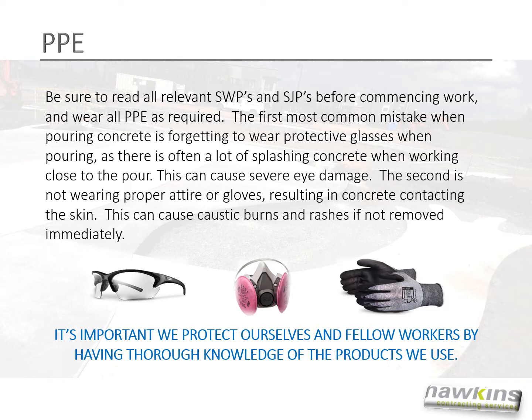The second is not wearing proper attire or gloves, resulting in concrete contacting the skin. This can cause caustic burns and rashes if not removed immediately. It's very important we protect ourselves and fellow workers by having thorough knowledge of the products we use.